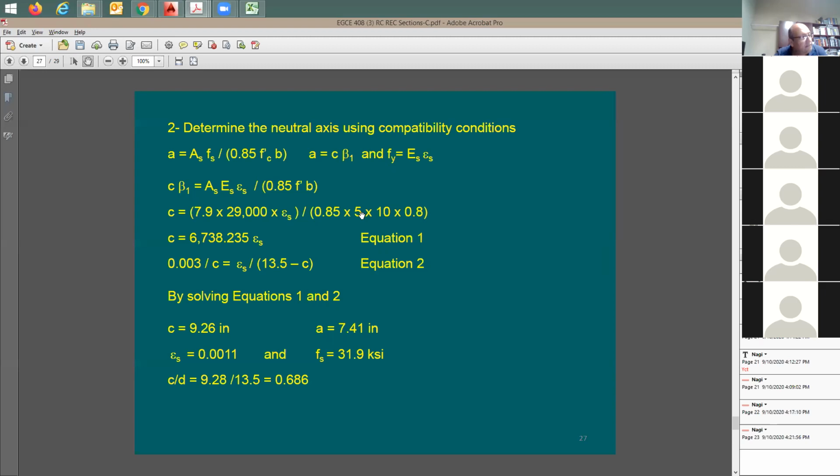Because we have the modulus of elasticity in ksi, so it's okay. This is correct. Absolutely. If I put this modulus of elasticity in psi, I should use this in psi. So I've got to be careful because I need to balance the units. In some equations, it's going to be simple if you like to do it this way. But if the equation includes the square root of f prime c, you cannot do it. You cannot do this straight.